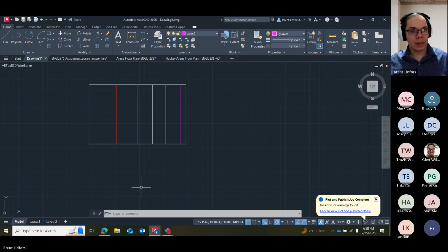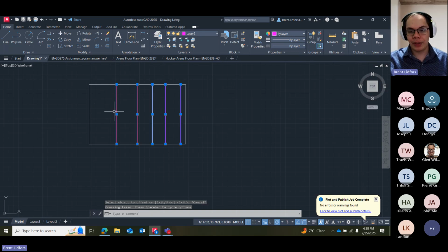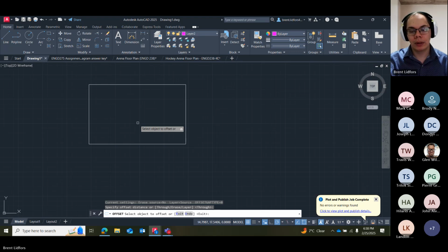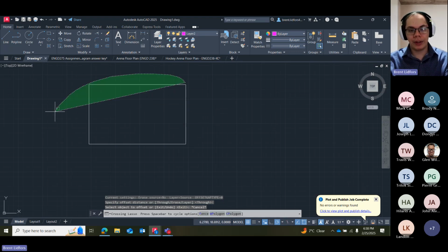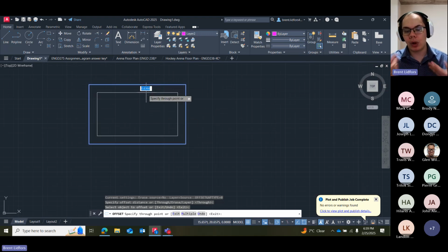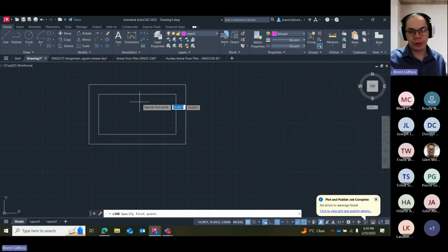And of course, with offsetting, if I choose to offset any polyline, if I join this rectangle again, if I choose any polyline, it will offset all sides of that polyline equally. So if I type in one unit offset into the rectangle, all the distances of all these sides should be 1 unit. So the top here is 1 unit away. The side is 1 unit.